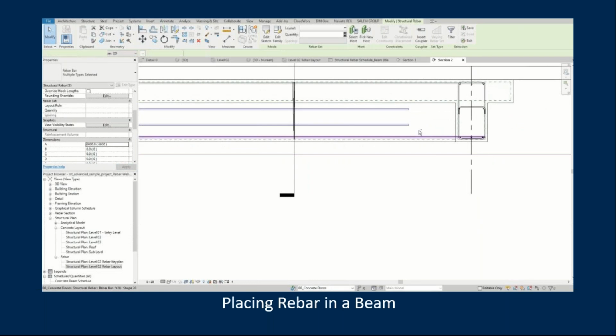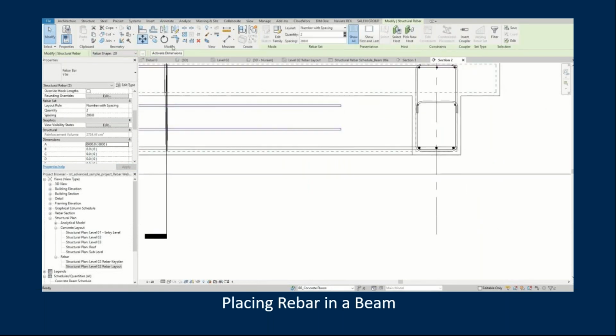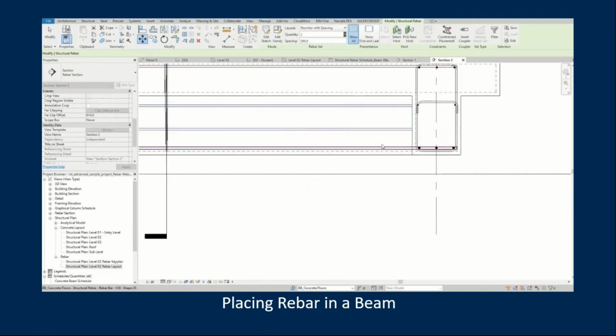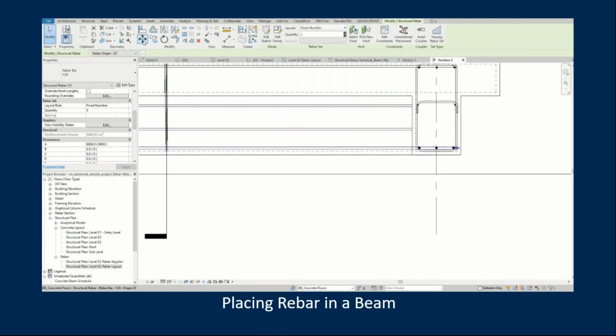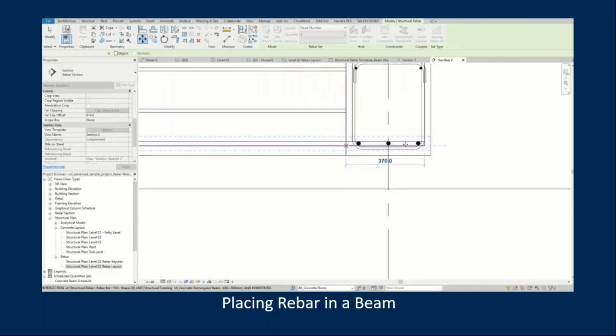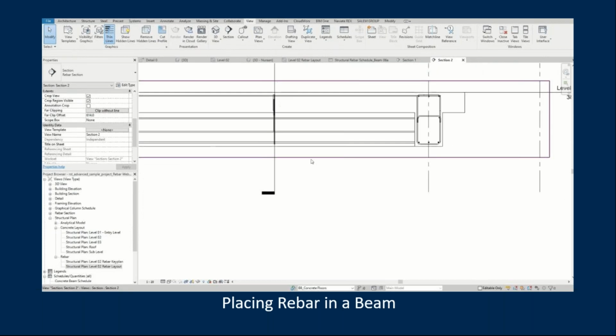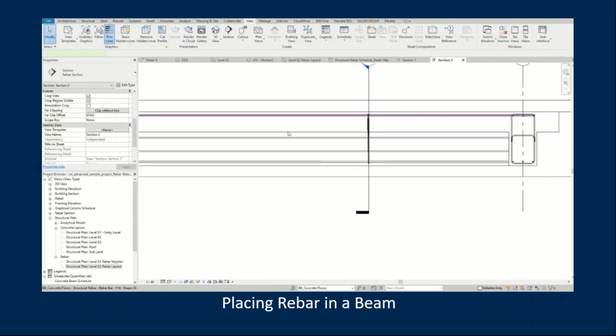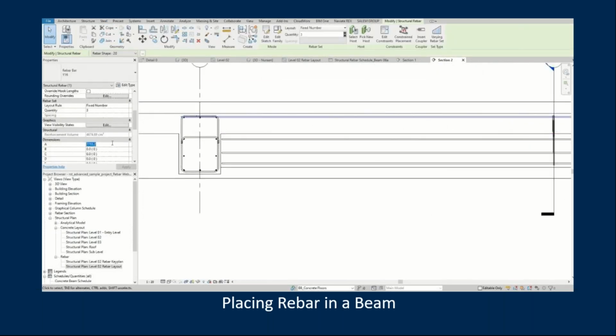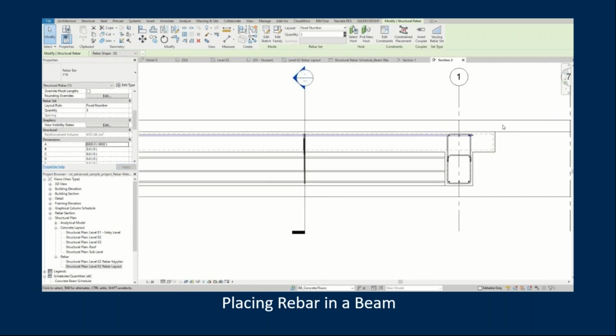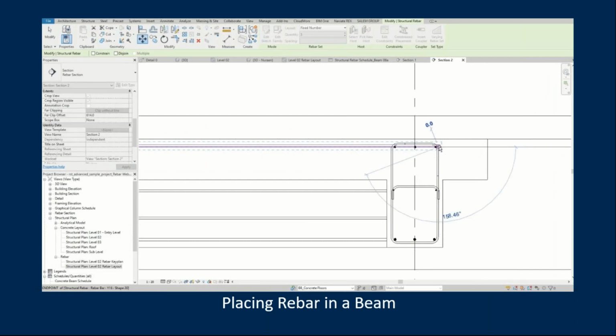And so that rebar is actually just in the span of the secondary beam. Okay, otherwise, we're going to end up with clashes, and then afterwards we'll just add some stitch bars or some hooks at the end that will tie into the primary beam.